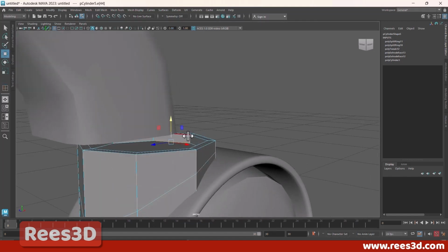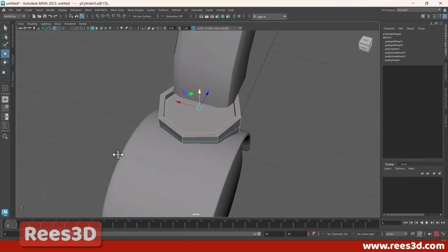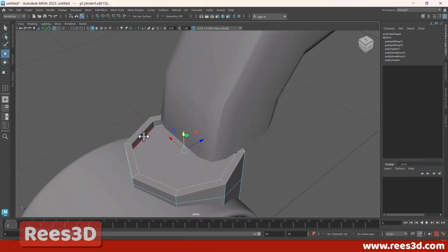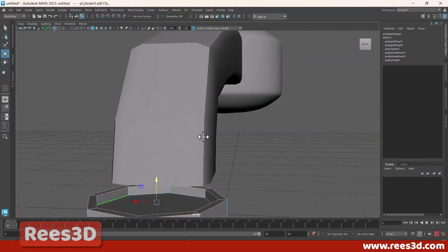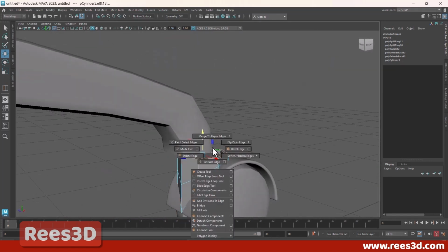So let's say double click on this one, and actually I need to select all these guys as well because they're not showing up. I can actually select them one by one. If I had one more set of edges or faces inside that, it would show up to be selected as an edge loop, but for now I have to do this manually.